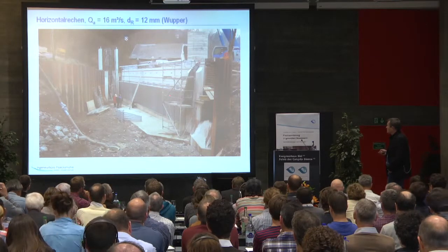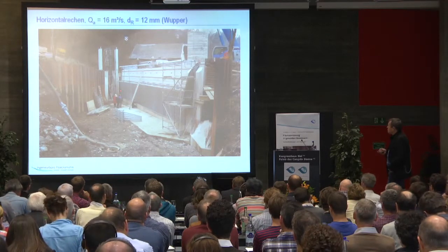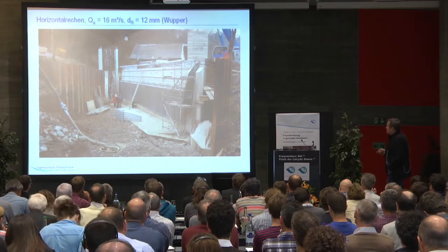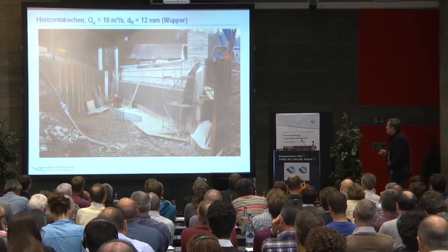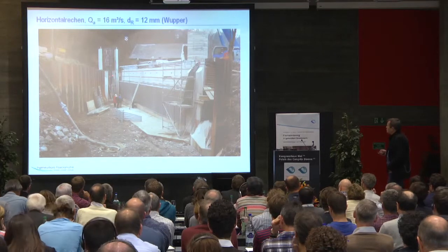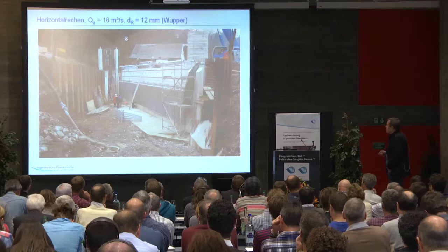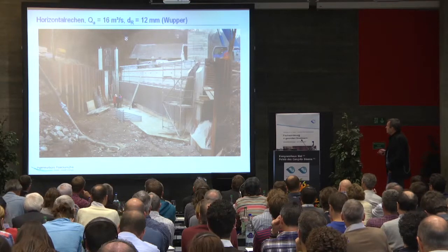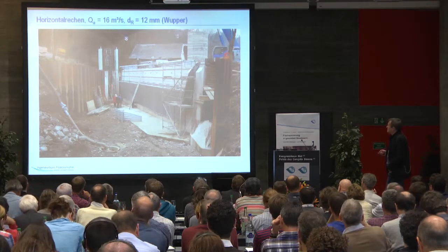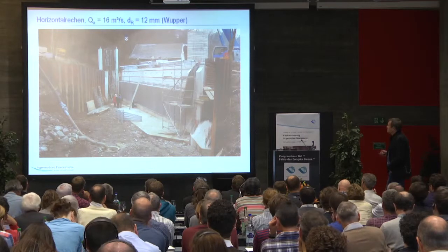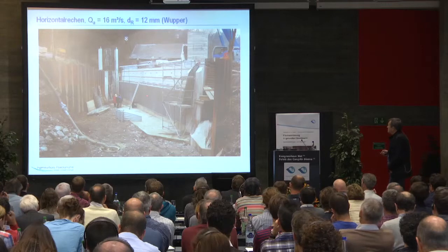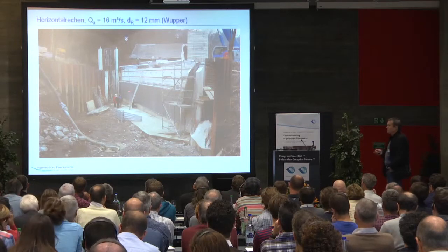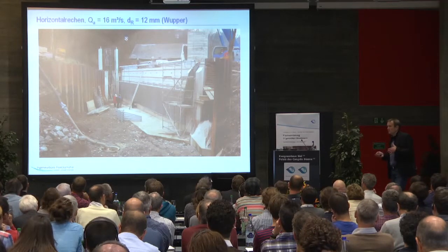And here we wanted to protect salmon smolts. We have a screen here with 12 millimeter bar distance, and then we have certain gates making it possible that the fish is let into a bypass. And we have a flap up there controlling the flow.